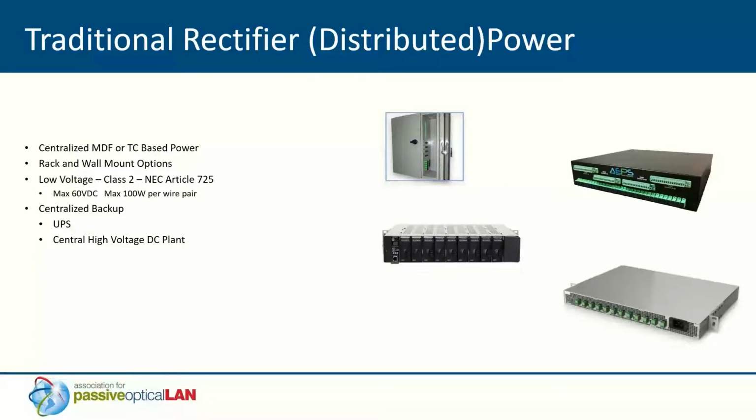It provides for a centralized backup in one of two ways. It could be a UPS located in that MDF or IDF, or a centralized DC plant, which we're seeing quite a bit of these days, utilizing a high voltage DC to the MDF or IDF, then being converted to usable power for the ONTs or end devices.